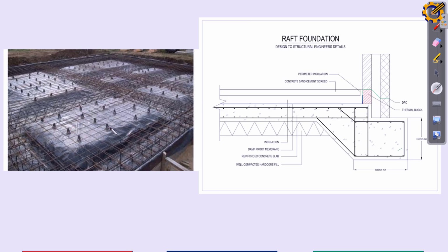And if, after rainfall, let us assume they haven't painted the wall, or even if they paint the wall and you notice that your wall is wet from the bottom, and you can't even put clothes inside the wardrobe because everything will get wet, then that house doesn't have a DPC. Soil water is rising from the soil, then penetrating into the building itself. So under normal circumstances, either being a raft foundation or slab foundation or whatever, a DPC should be introduced in between the flooring material so as to prevent the flow of soil water into the building.